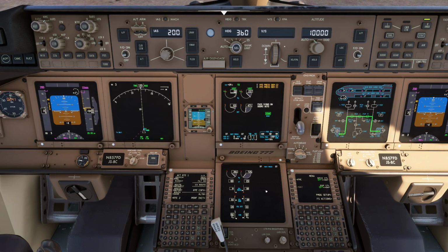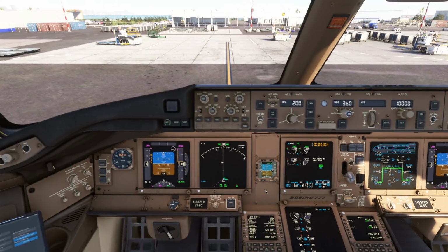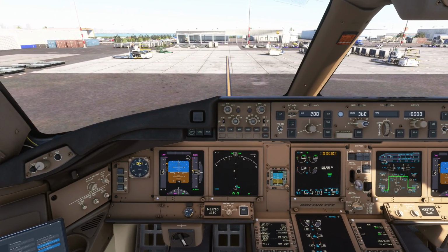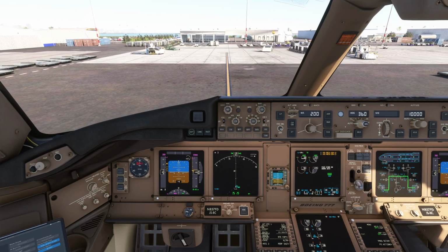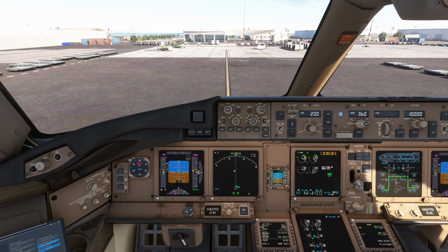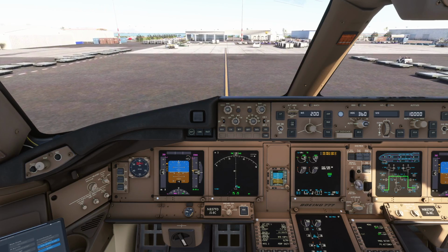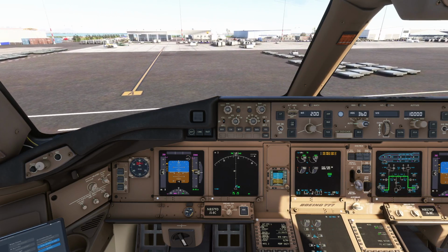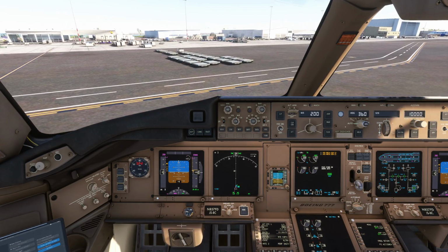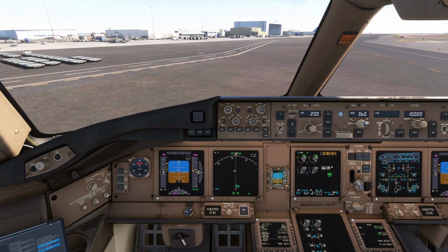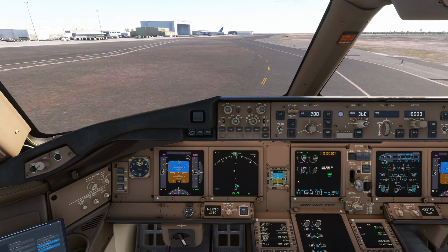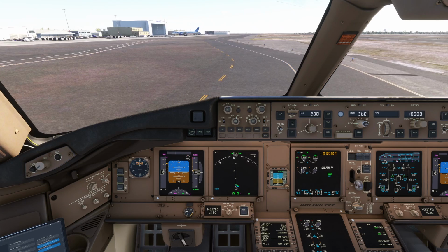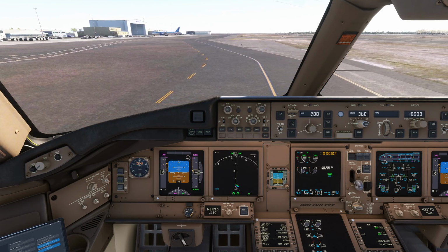Everything's operating as desired. And I'm going to go ahead and speed this up again just to make this a little faster. Engines, N1 is starting, the fuel flow, and the EGT, the engine gas temperature, is going up. All right, everything's all shut off again. The packs are off. This again is the 60-second delay.